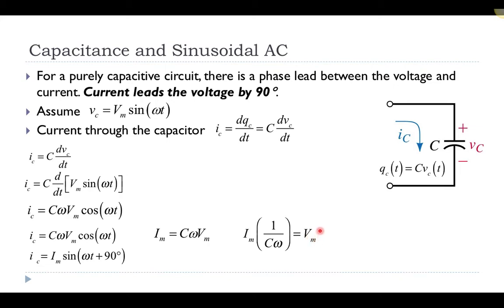So this looks similar to V equals I times R, where R would be in parentheses. But instead of it being the resistance, we say that it has capacitive reactance. And the capacitive reactance is just this term that's in parentheses right here. It's the ratio, 1 over the angular frequency times the capacitance. So what is capacitive reactance? Capacitive reactance is similar to inductive reactance. It's a measure of how much the capacitor is resisting the flow of current in the circuit.